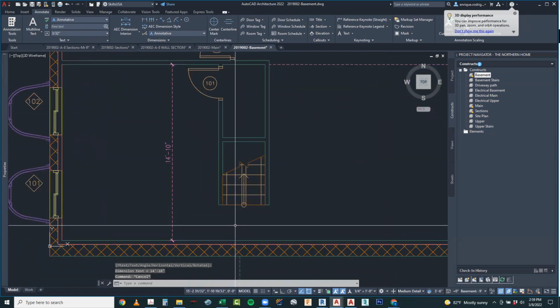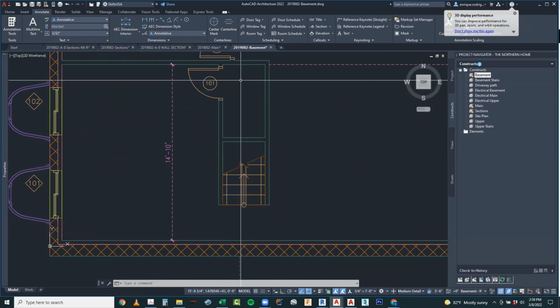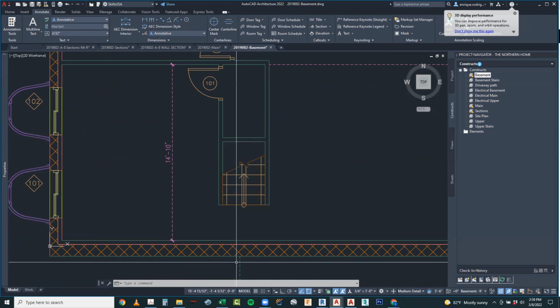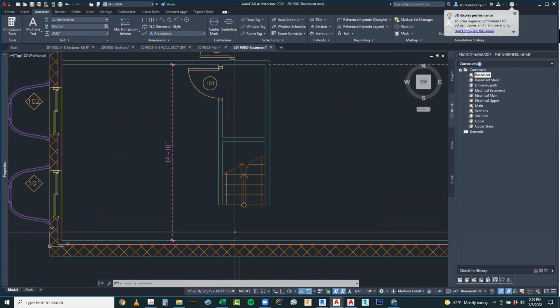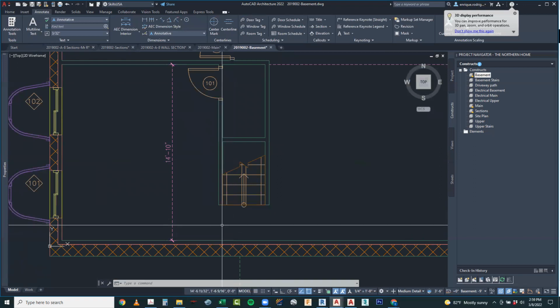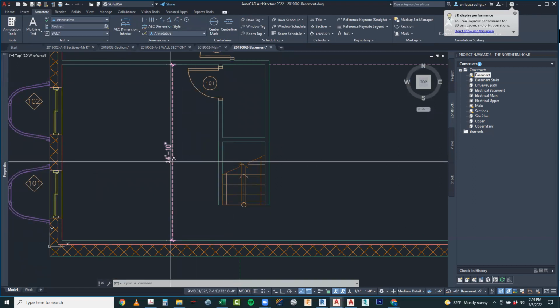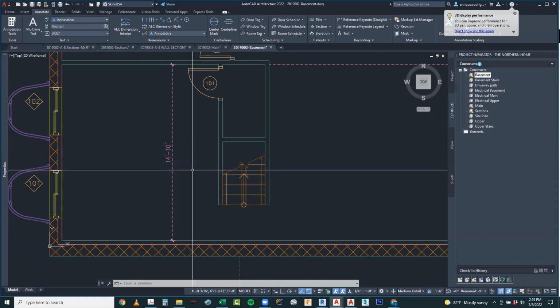Now, what we do want is that 3 feet here, minimum. And that's so if somebody's coming down the stairs, if they got a little bit of speed, they've got sufficient time or space where they're not going to smash into the wall. So we're going to give it 3 feet here. So we're going to take 14 feet 10 inches and take out 3 feet. That's going to leave you with 11 feet, 10 inches. Now we're going to convert that to inches. So how much does that end up being?